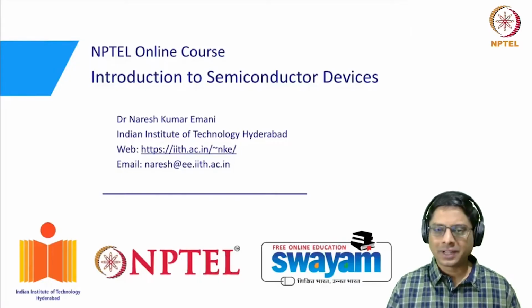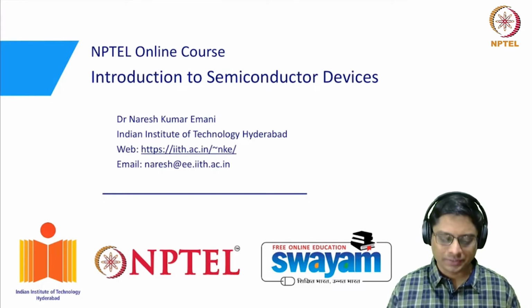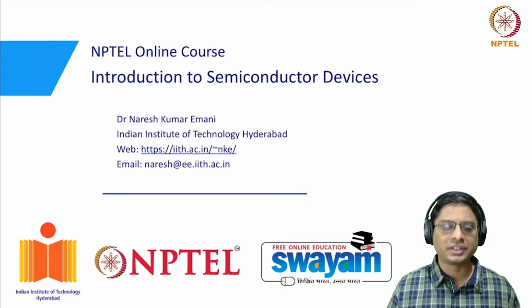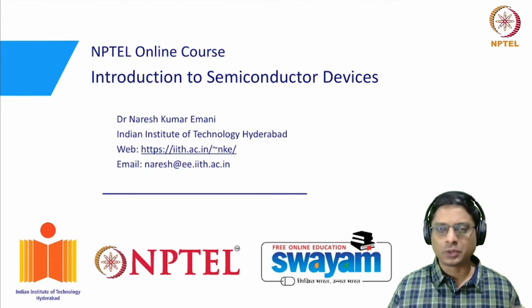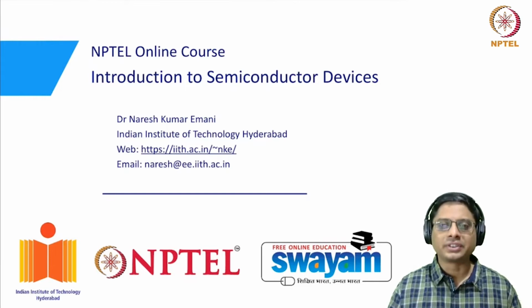All right, welcome back. So in the previous video, we discussed the two basic types of photodetectors, the photoconductive photodetectors and the photovoltaic photodetectors. So in this video, we would like to go forward. We were talking about improving the photocurrent that we produce in a photodetector. And one of the key parameters was to increase the width of the depletion region in a photovoltaic detector, or the detection region we want to increase.